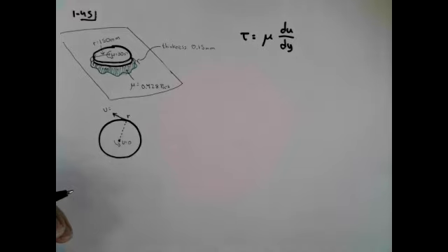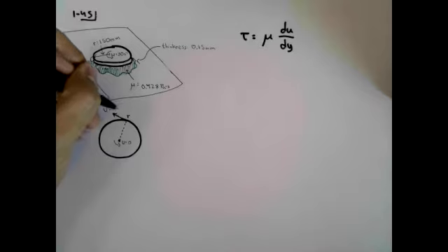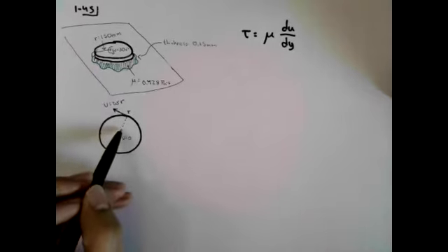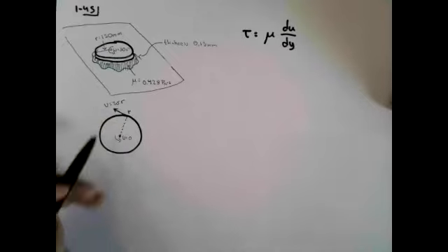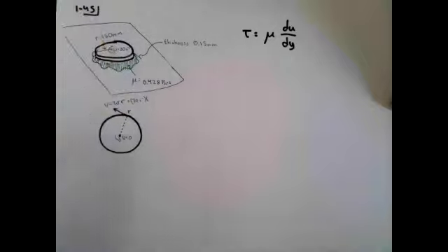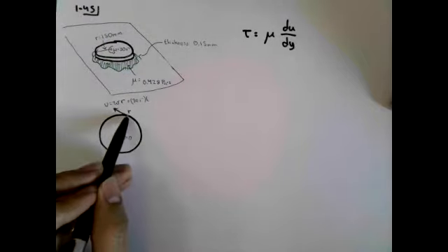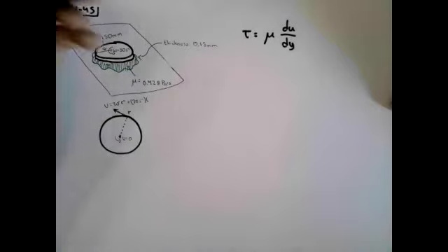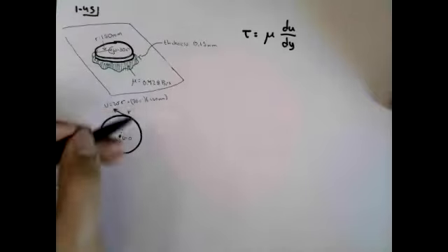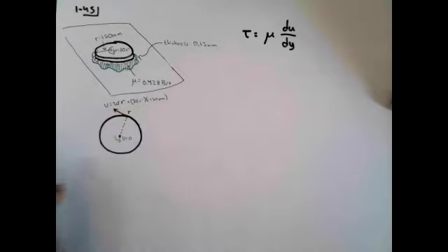Will you multiply it by the radius? Exactly. We know the velocity will be equal to the angular velocity times the radius, or in this case, the radius represents your distance along the r-axis. So for the velocity at the edge, we would have our angular velocity of 30 radians per second multiplied by the distance between the center and my edge, which is 150 millimeters. So it'll be 30 times 150 millimeters per second.